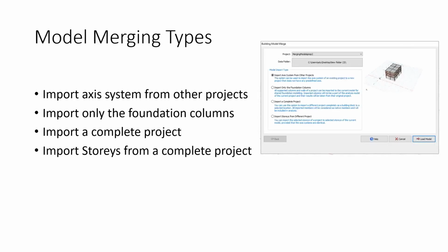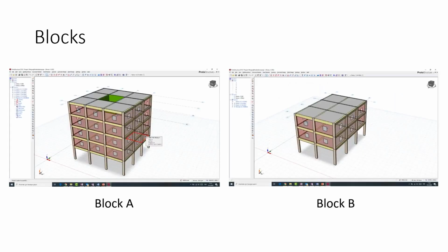We have 4 different merging options. I will be explaining these during the demonstration. We'll be working on these 2 blocks today, block A and block B. We'll be merging these 2 blocks for combined foundation design, and we'll be importing block B to block A for story import.